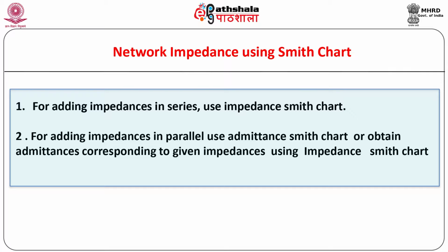Namely, for adding impedances in series, use impedance Smith chart, that is Z Smith chart, and for adding impedances in parallel, use admittance Smith chart or Y Smith chart, or you can obtain admittances corresponding to given impedances using impedance Smith chart also. Let us try to understand these principles with the help of a simple example.